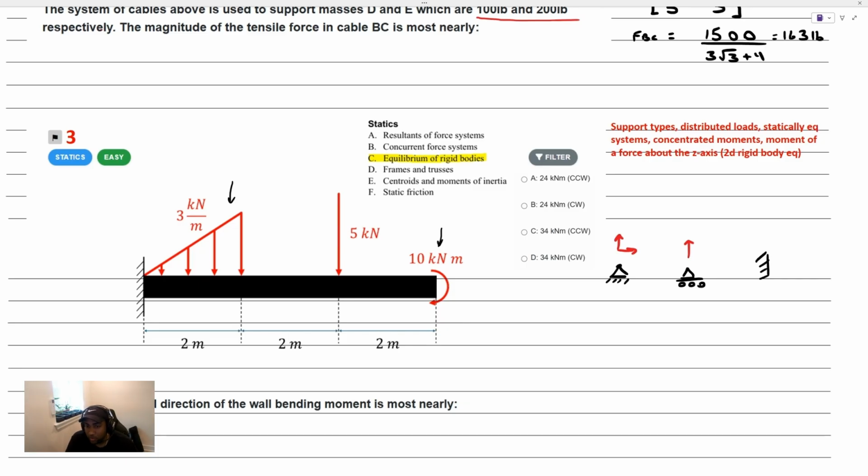Now, when you restrict displacements, you introduce forces. When you restrict angles, you introduce moment reactions, right? So, of course, at that fixed end for a cantilever, for example, we'd have no displacement. So, of course, we'd have X and Y reaction forces. But additionally, there's no angular displacement at a fixed end or welded location. So you'd expect additionally there'd be a moment reaction. Okay, so that was a quick review of typical 2D supports you see on the FE exam.